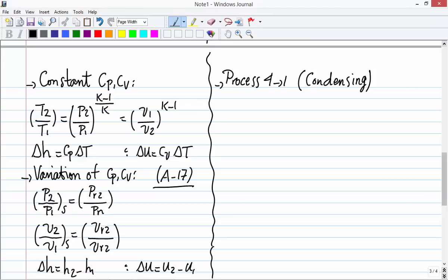If you are solving a Rankine cycle, oh my God, I've seen a lot of students that get confused and they don't pay attention that they're solving for a Rankine cycle, and they use CP, what do you mean? It's like you have liquid. All that we have been talking about in this course, in most of the cases, CP was for gas, right? And now you're talking about a pump, so how do... Don't get confused, okay?